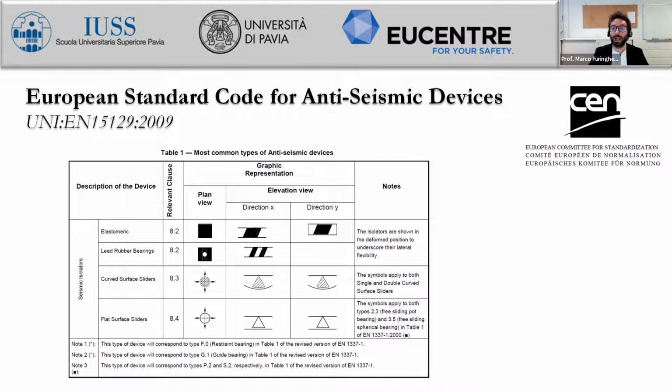So maybe we have 25 structural bearing points, and then we get maybe 10 rubber bearings according to our design procedures. This means that we need 10 rubber bearings of certain sizes with some mechanical properties to have exactly that period with that damping and to provide a certain value of lateral stiffness.